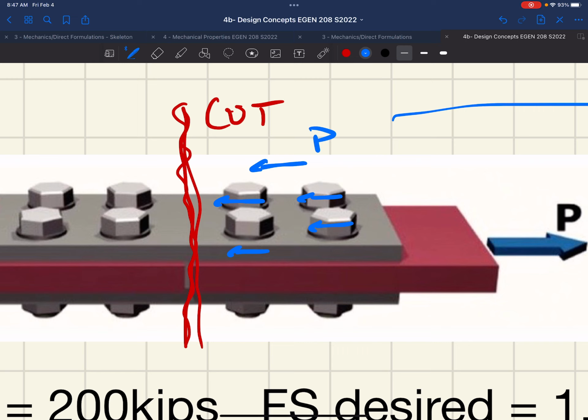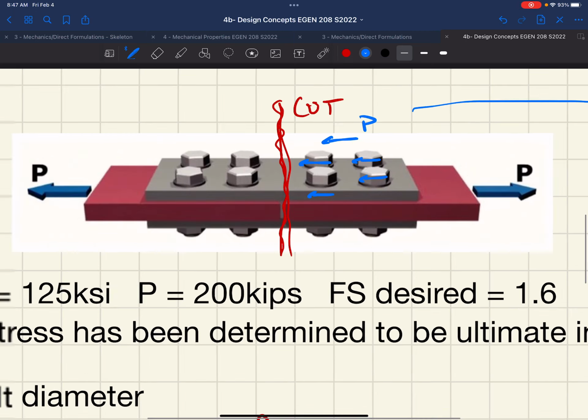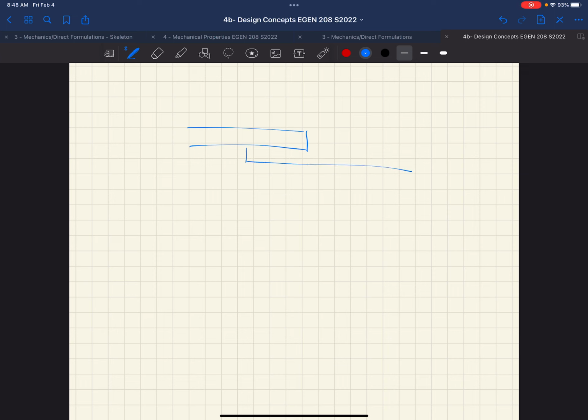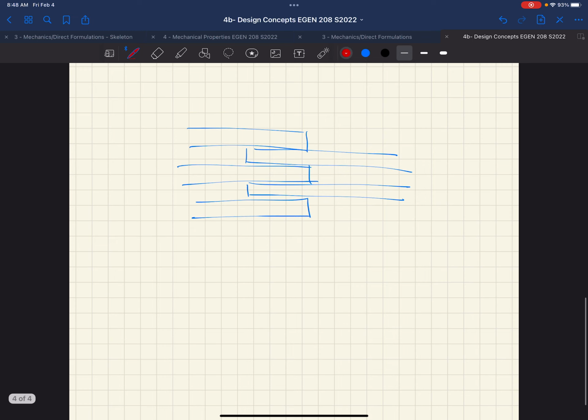So the only way you have like 3 shear planes is if you had it in like 3 different ways? You could definitely do that. You would have to add additional splice plates, which would, I mean, a 3 connection would look something like this, right? And you ran a bolt through this entire thing. Oh, 3 would be tough.